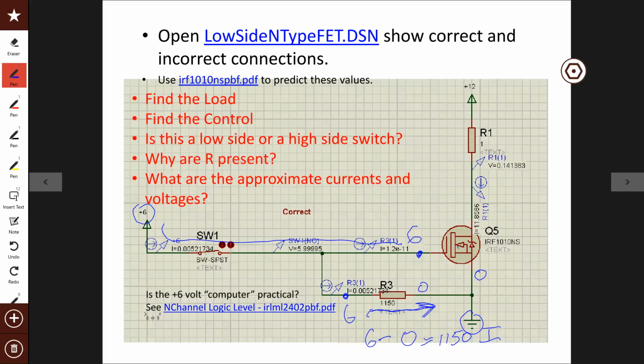Okay, now because you have a high voltage here on the gate compared to the source, which is right here, you're trying to force current across that arrow. That's the way I remember it. So in other words, you've turned on this switch. If the switch is on, the voltage here is going to be approximately the voltage here, which happens to be 0 in this case, right? Now if I put a battery in here and this was 3 volts, or 4 volts, whatever, approximately the same thing is going to be up here, as long as the FET is on.